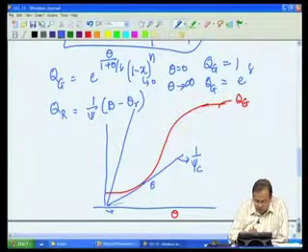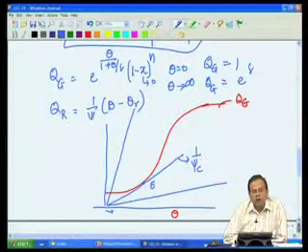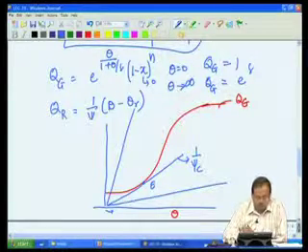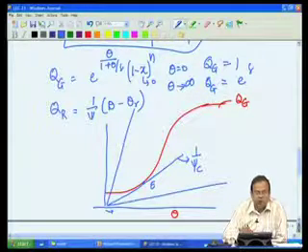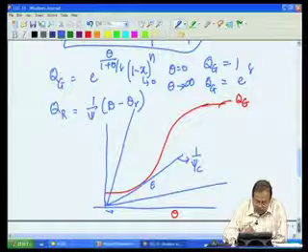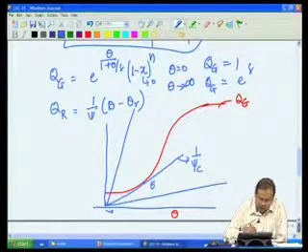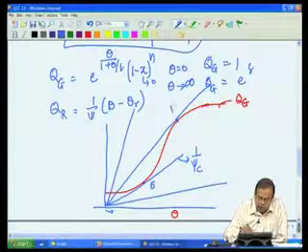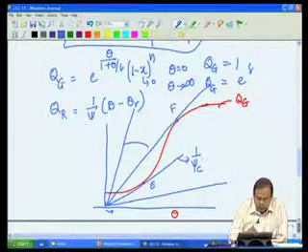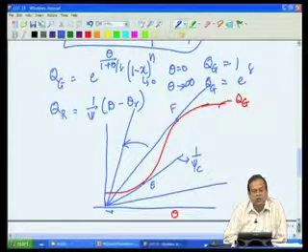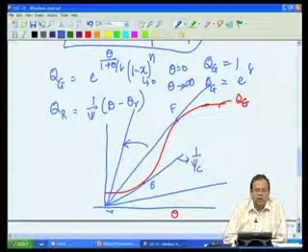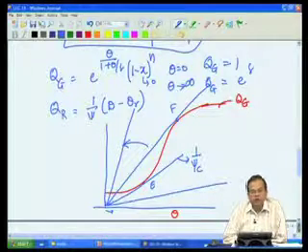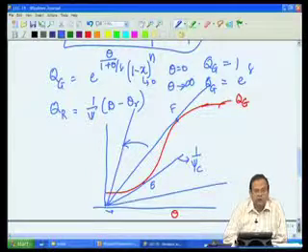then any line which is below this is a sure shot for runaway reaction. So, this gives me one bound on what is the limit of my safety operation. That is, if this heat removal line is a tangent to heat generation line at point E. Similarly, I could have another tangent at point F. I know if my curves are on this side, I have a safe operation. So, in short, we can now therefore find out the range of operations for which my operation will be a runaway reaction or a safe operation, or maybe runaway, maybe a safe operation.